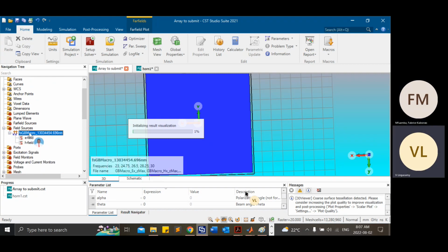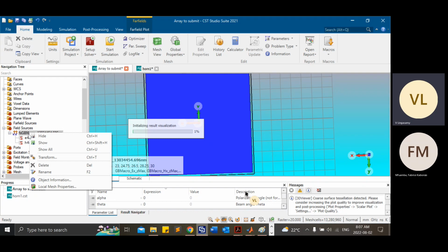If you are exciting a plane wave, this is the one, just above the reflector array. My question was, do you think practically it is good to feed an array with a plane wave? Practically, no. It is not possible, because of the focal distance we are maintaining. With the focal distance we have a taper, right? It will not be a plane wave.